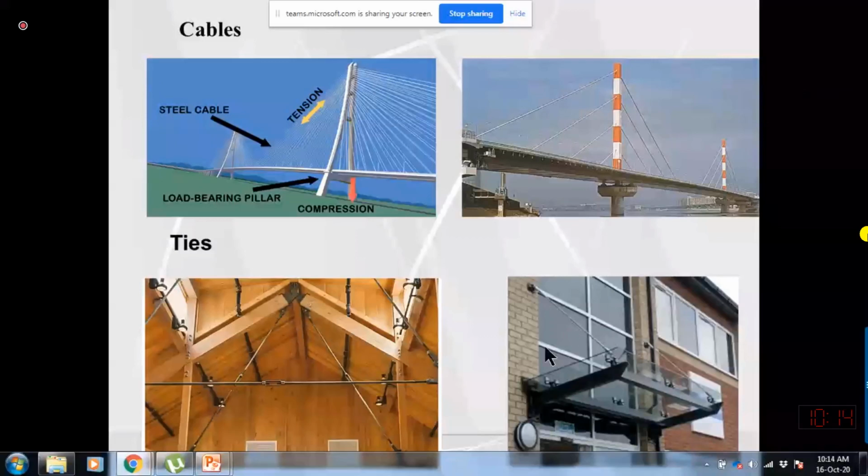We know the length of this rod, and we know the total load acting, so we can compute the total force in this rod from our structural analysis. If we know the material strength, we can compute the minimum diameter required to resist the dead load of this shade safely. So if the diameter required is 12, we may provide 13 or 14, but we may not provide any larger diameter due to economic reasons.